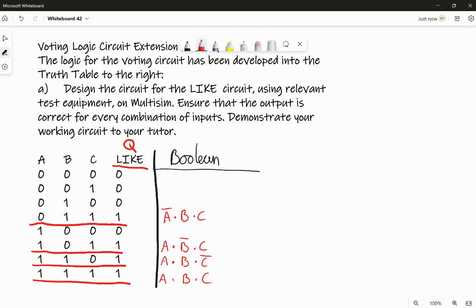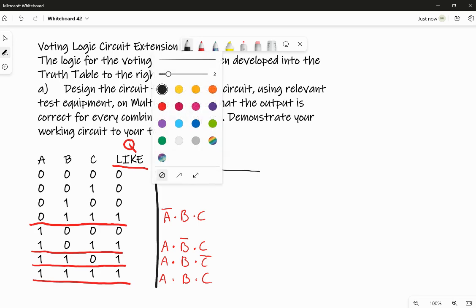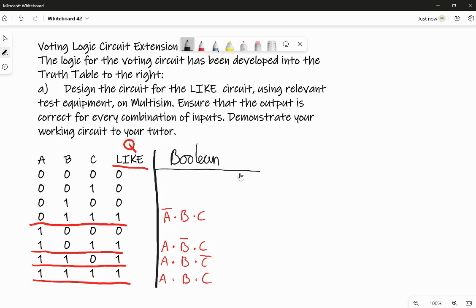In order to get our completed Boolean expression, the next stage is to simply write all these out, because what we're saying is that to get a 1 on the output of the circuit, it's going to be this one, or the next one, or the next one, or the next one after that. And we need to indicate that it's this expression or the next expression by using the correct symbol. Now, as we figured out last week, the correct symbol for OR, because it's electronics, it's complicated, is actually a plus sign.